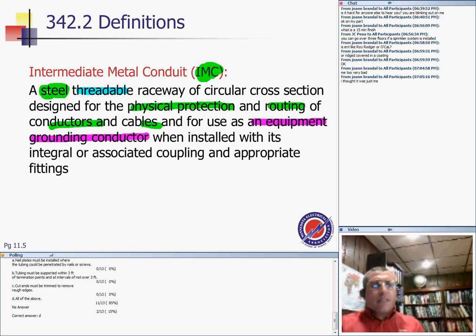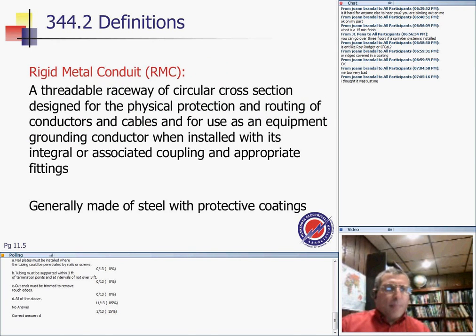Very clear cut about IMC. Any question about this? Very clear. No aluminum, there is no brass, there is no other conduit. It's a steel conduit. Done. And guys, some of you will say, what's wrong with that steel conduit? Well, there are other applications where you might need something other than steel conduit. Like if you have steel versus aluminum. Aluminum is very light. If you have an indoor application, aluminum rigid would be very nice because it's not heavy.